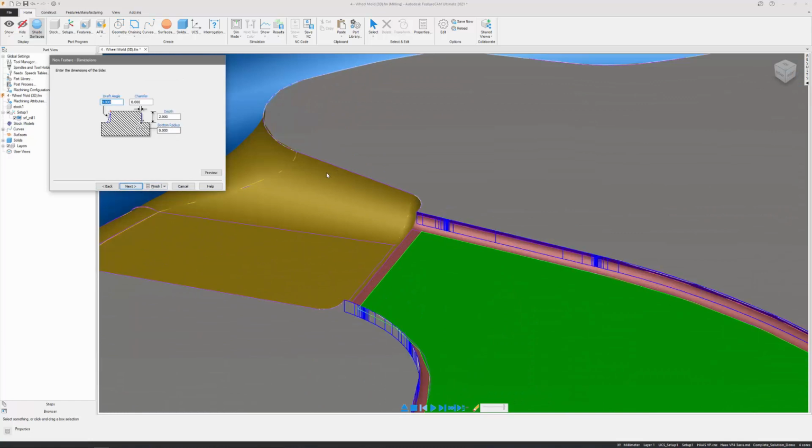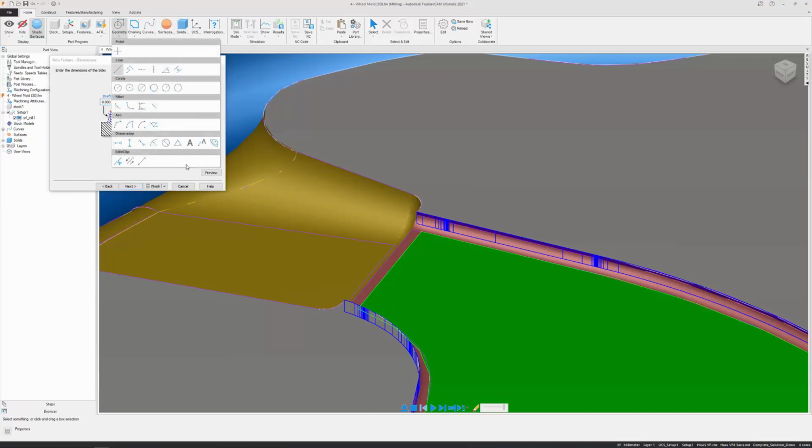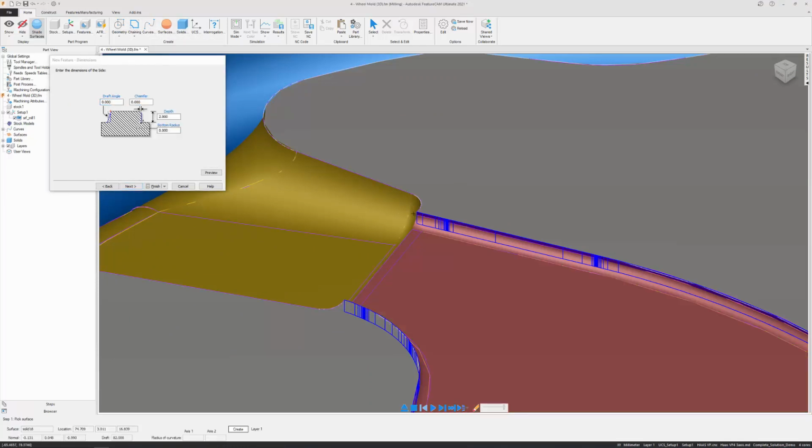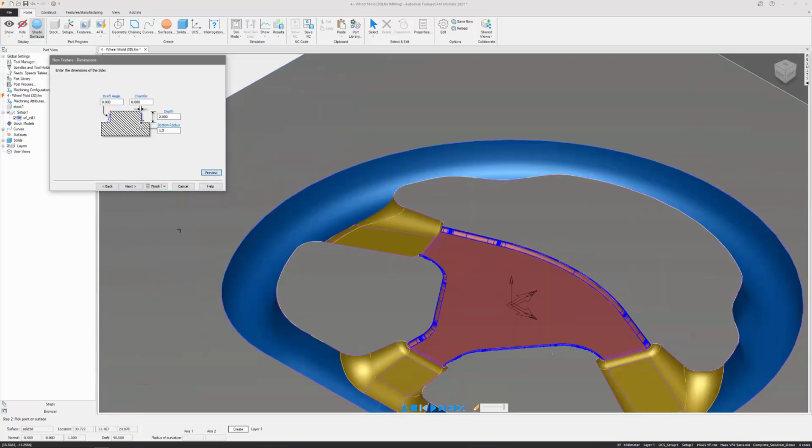And then finally, we're just going to add this bottom radius. Now, I don't quite know what this is, so I'm going to utilize the curvature tool in the geometry tools. If I just select this face, I'll notice in the bottom there, it says 1.5 millimeter radius. So it's just as easy as entering that here. Awesome. That's exactly what we want.